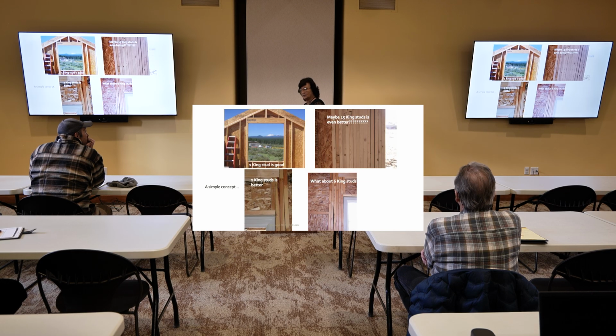So we don't necessarily need all of this, but if it's there, you're going to have to calculate that into the U-factor of your wall. Because you can say, I have a wall with R20 insulation, but you don't.